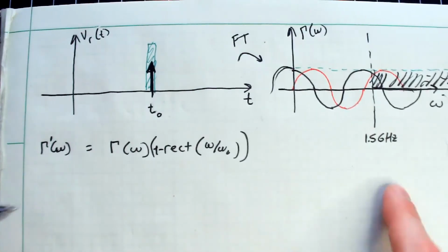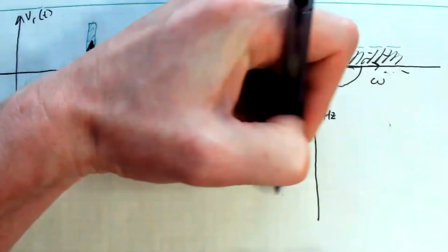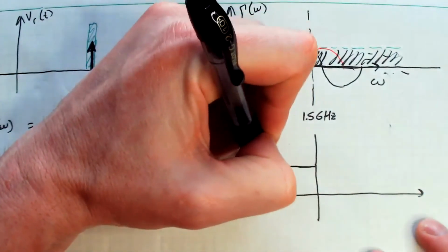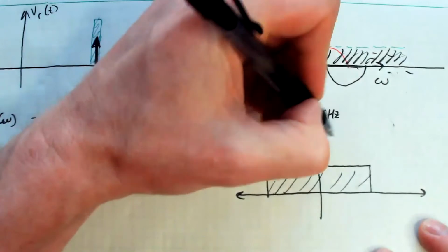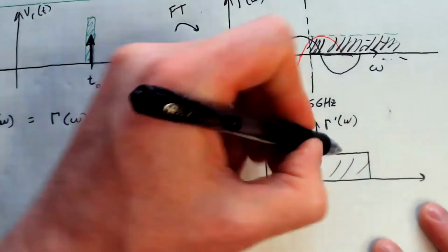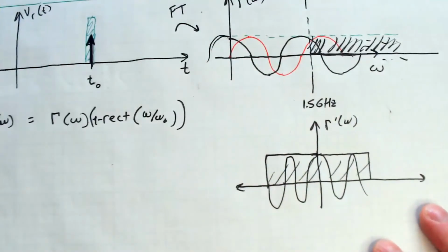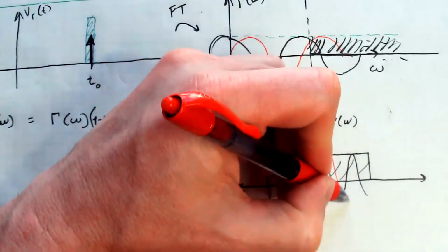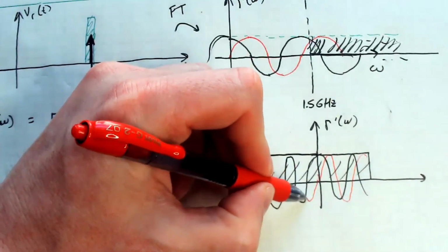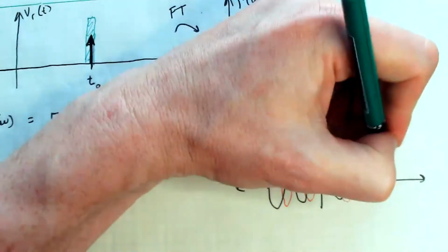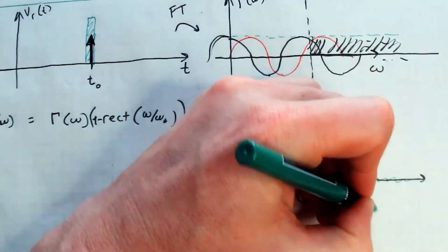And if you want to be extra accurate, we have to imagine this thing having a negative frequency. So a better way to visualize it, being a little bit more mathematically rigorous, is you have this band limited window function like that. So here is my gamma prime of omega, and then there's my signal inside here doing this thing, and then of course the imaginary part doing its thing like that. I can draw that by hand, and then it abruptly turns to 0 for all these values after my bandwidth. So I'm going to write omega naught here like that.